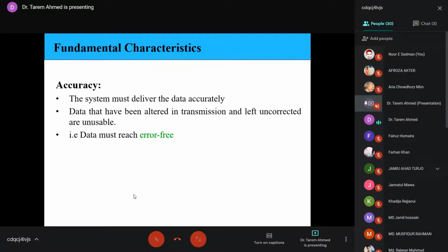You cannot make the error zero. Every transmission line is given a quality value based on the probability of error. Typically, it's in the order of 1 in a million, which means 1 in a million bits gets flipped. But you cannot make it 0. There are two avenues in which error creeps in. One is noise, the other is attenuation.